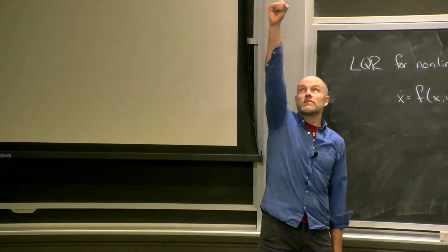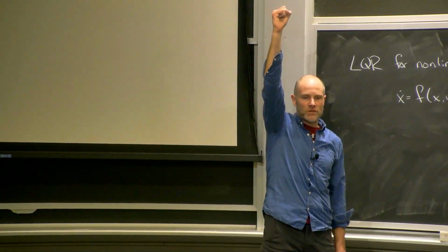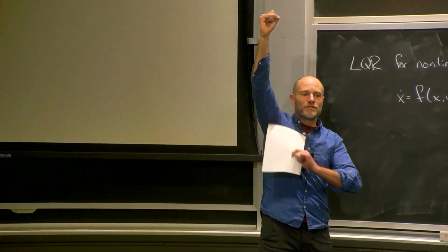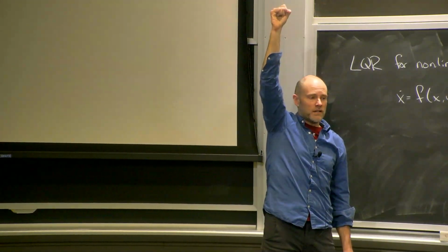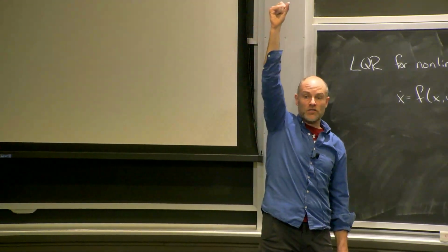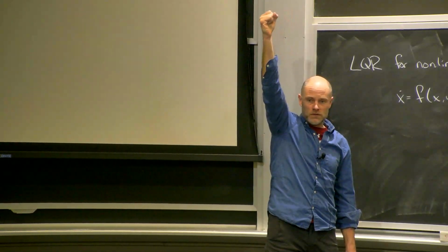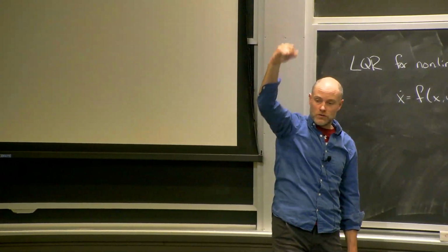So let's pick a linearization at the top. Okay, so x will be, let's say, theta for the first link and 0 for the second link. The second link is a relative angle. Okay, and then u will be all zeros at the upright. When you're actually at the top, you don't need to torque.